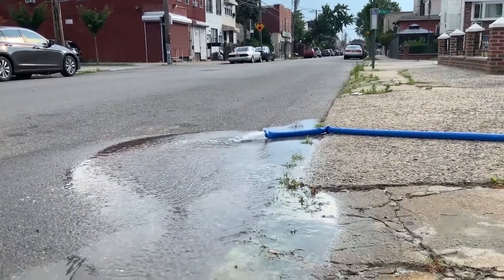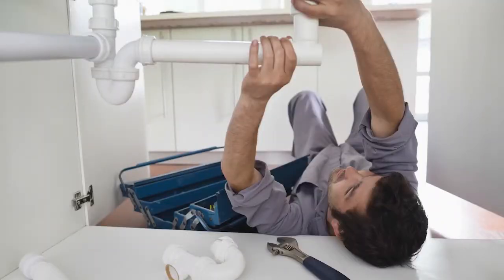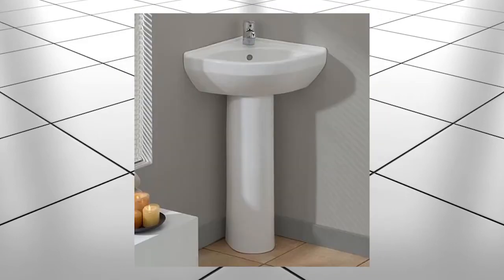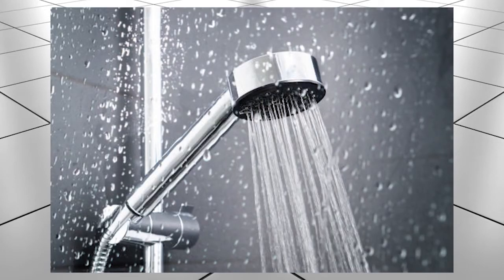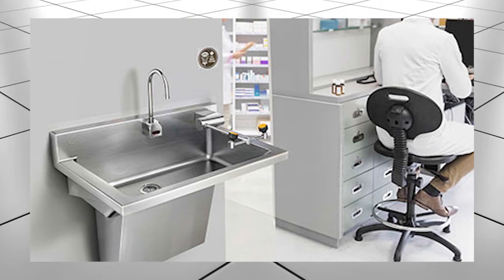Waste pipe is classified into 2 types, the direct waste and indirect waste. Direct waste is one with terminal directly connected to the plumbing system, and these are urinals, where pedestal, stall, and trough are its kind. The bathtub, under it are sitz, foot, and bidet. Lavatories like wall hang, pedestal, and 2 pieces. Sinks like slab, pantry, and kitchen sink. Showers where there is a single stall or a gang. The drinking fountain, laundry, laboratory, and hospital fixture.